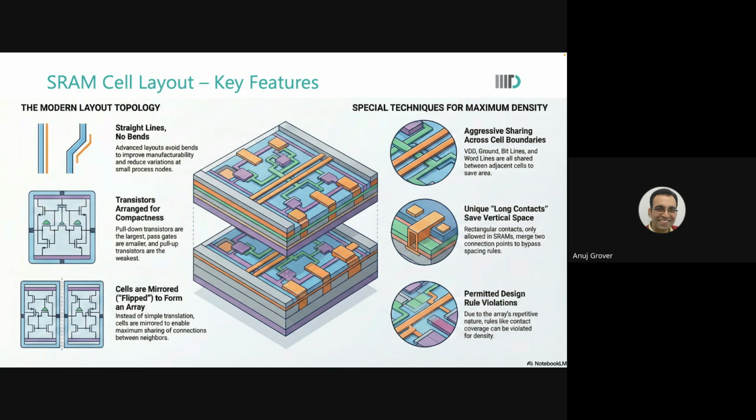What this also leads to is that since we are violating the DRCs now, the transistor behavior will change. And therefore, SRAM devices, the six devices of the SRAM, have a different model than the regular NMOS and the regular PMOS. How many of you have opened the model file that we have in 65 nanometers? You all worked on 65 nanometer in the DVD course. How many of you have opened the spice.lib, the model file? We use NSVT, NHVT, and all that stuff.